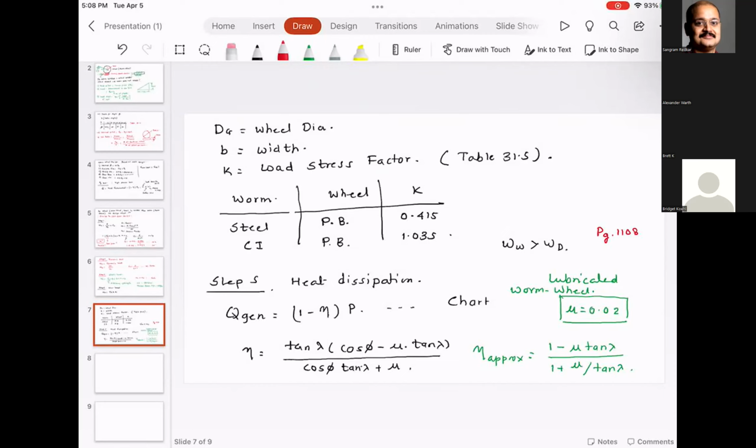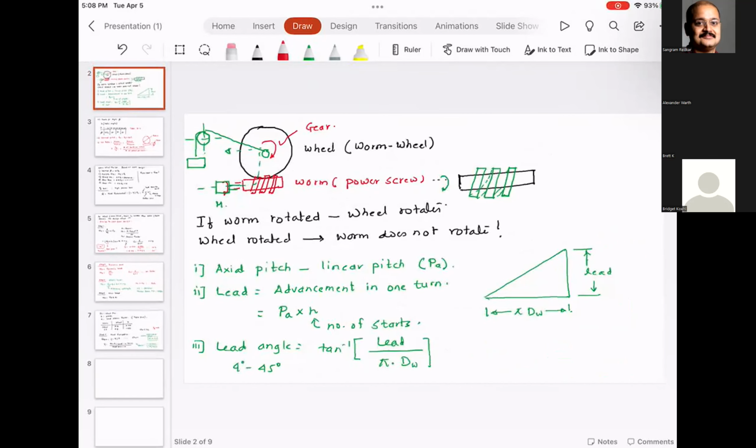Worm wheels have a lot of applications, and depending upon what you are trying to achieve, you can use the appropriate gearing design. The most important thing about the worm wheel is that the shafts can be perpendicular to each other, but they don't have to be in the same plane. In the configuration diagram of a worm wheel, the center line of the worm is perpendicular to the center line of the wheel, but these two center lines are not in the same plane.